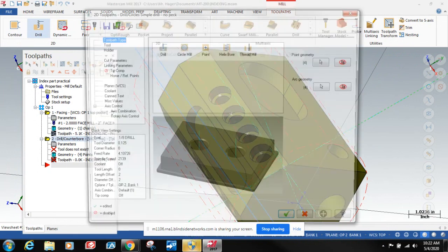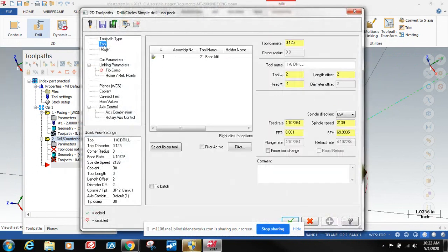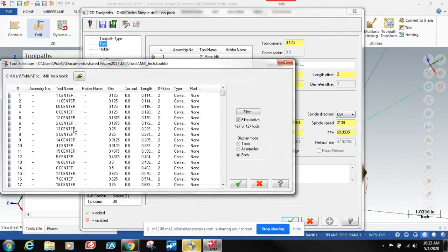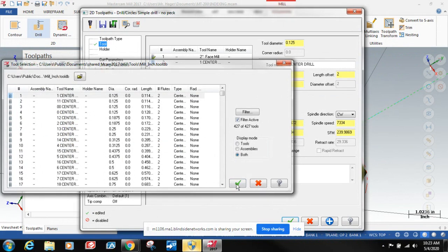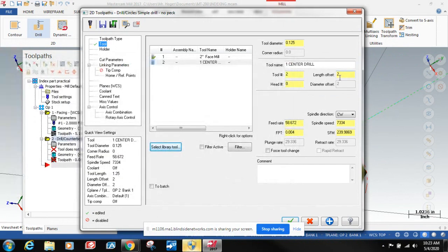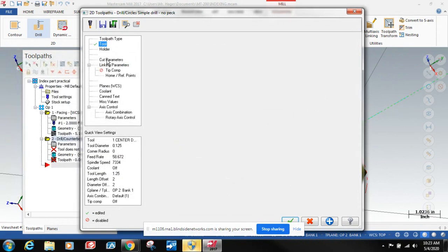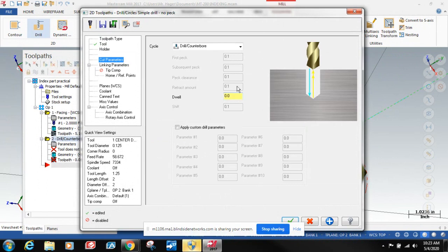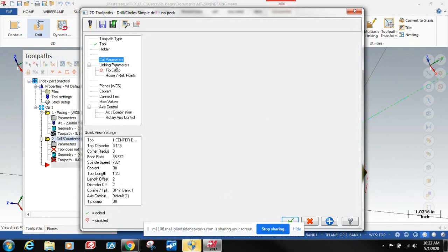My solid imported wrong, so I had to do it again, but it worked the second time around. When you did display, did you do the shape from the solid or from the cylinder? Well, the cylinder is just simulating the stock that is going to get cut out. Once you select the milling machine, you just have to select the plane that you want to machine.